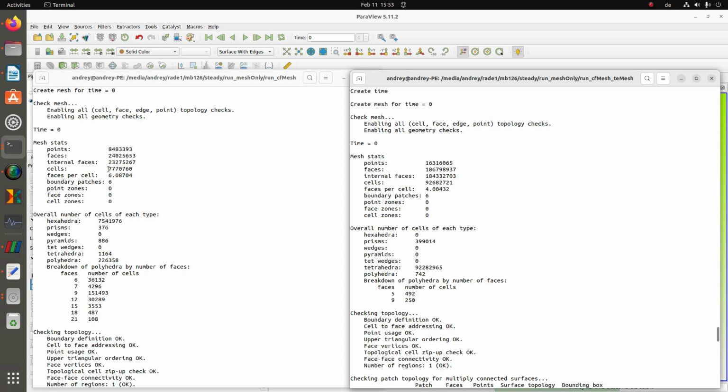Now imagine for a moment that your computer has to calculate 100 million cells instead of 10 million cells. That is why I try not to use Tetra mesh. That means that I don't like the Workbench mesh generator because it takes mostly Tetra mesh, used in Ansys Fluent.